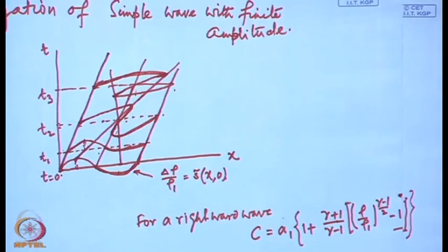And the intermediate part is where the diffusive actions are considerable. However, they are not exactly in balance with the nonlinear steepening effect. The states are non-isentropic, and they can neither be considered within the isentropic relations nor with the shock relations, and the complete unsteady equations including the viscous and heat transfer terms are required to analyze that part. That will be somewhere between T1 and before T2.